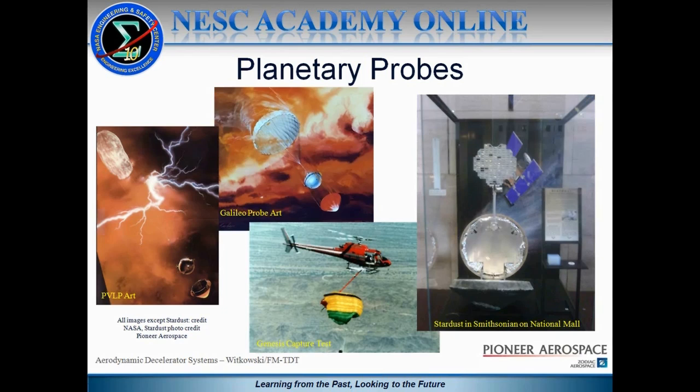The Genesis probe was expected to use a modernized version of mid-air retrieval for its recovery system in 2004. Unfortunately, a misplaced acceleration switch prevented deployment of the decelerator system that included a 39 square meter parafoil. The Stardust probe used a 7-meter triconical parachute as its main landing decelerator that successfully returned cometary particles in 2006.